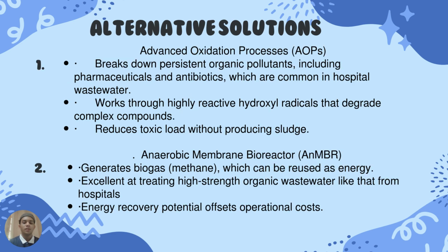So for the alternative solutions, we have number one, advanced oxidation processes. It breaks down persistent organic pollutants, including pharmaceuticals and antibiotics, which are common in hospital wastewater. It works through highly reactive hydroxyl radicals that degrade complex compounds, and it reduces toxic load without producing sludge.